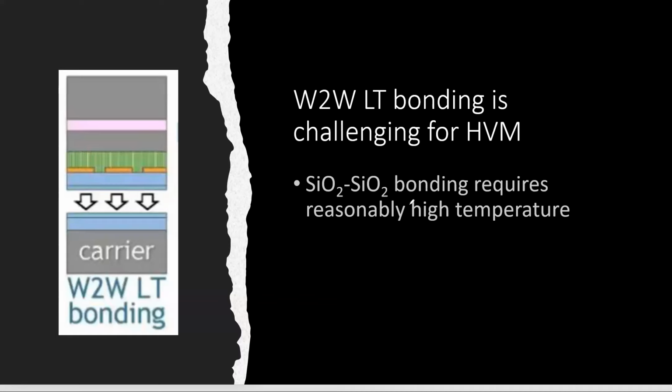That's the key. In the Soitec SOI business, their bonding temperature is reasonably high, so they can bond very clean, very nicely, and the surface becomes very flat. If you do low temperature bonding, I don't know what you mean by low temperature bonding. You could bond anything without even heating up. If these two surfaces are perfectly clean, you could bond them at room temperature very easily. Okay. And you will not open it up, but it just will not survive later.